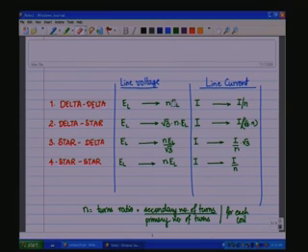In the case of the delta, for the same power and voltage ratings, this is supposed to have a higher core cross section area to withstand a higher voltage, but the gauge of the wire will be thinner, and in the case of the star it can withstand a lesser voltage, but the gauge of the wires will be thicker. Anyway, depending upon the application, the relationship between the voltage and the currents, one of the 4 types of configurations or topologies can be chosen.